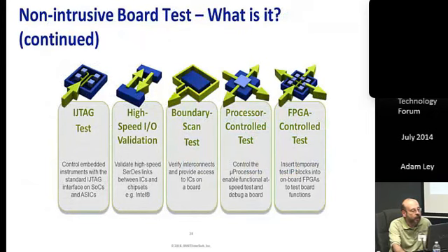We've mentioned all of these in turn, and I'm not going to trouble you to read the detail here, but there's a range of methodologies and technologies available, starting with IJTAG, which accesses the chip-level embedded instruments through a JTAG network, high-speed I/O validation, which is the BERT-like testing that we talked about, boundary scan for structural testing, processor control test for bottoms-up functional test, and FPGA control test.